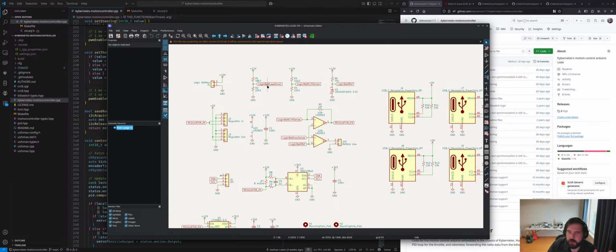Basically, there's a low battery sense input and a battery critical input. One trips at, I think, 3.3 volts per cell of the LiPo, which I believe represents about 90% of the battery used. So that triggers a low power battery logic power low sense signal. There's a logic battery critical signal, which I believe I have set at 3 volts per cell, which makes sense because it's a divide by 3 and it's a 3-cell battery.